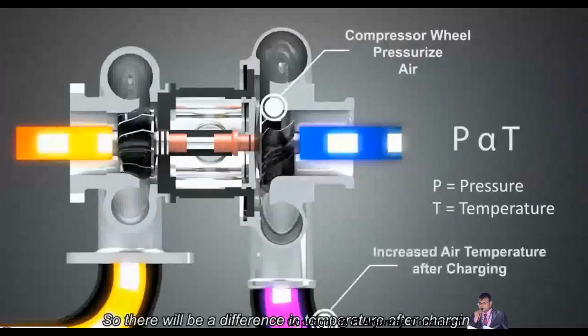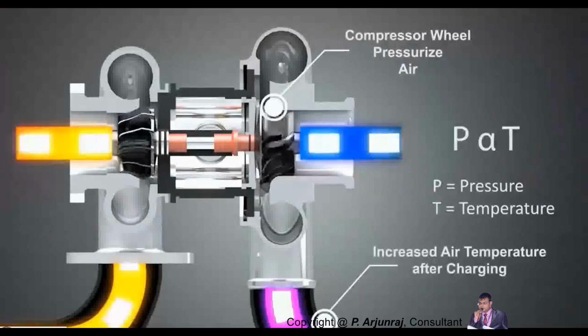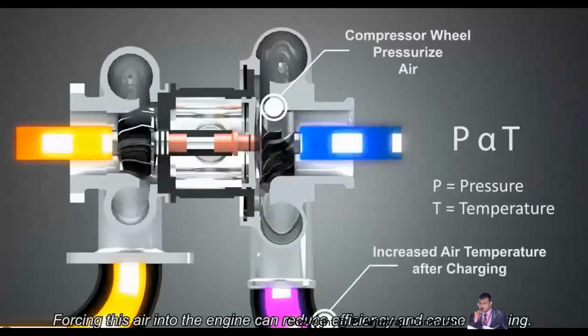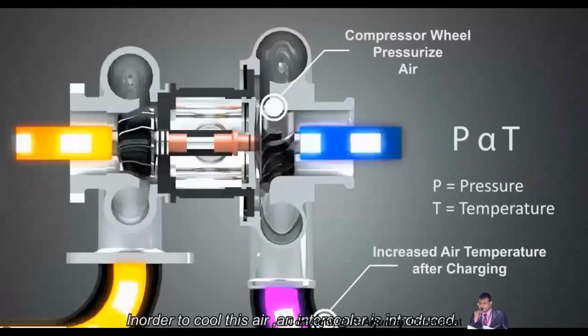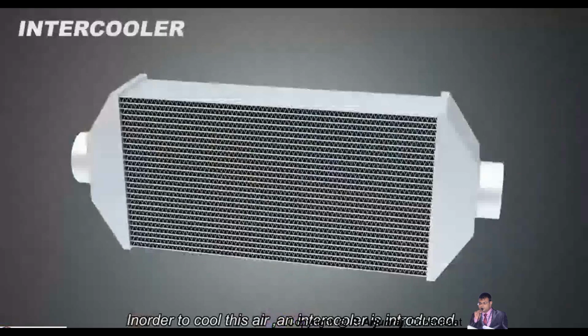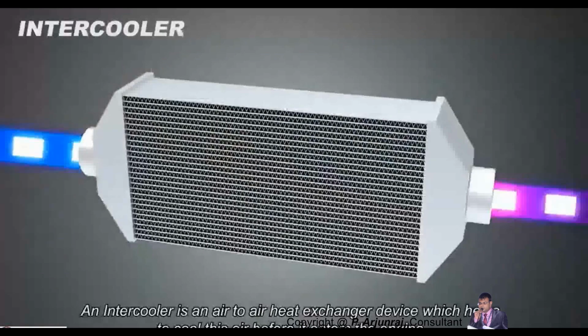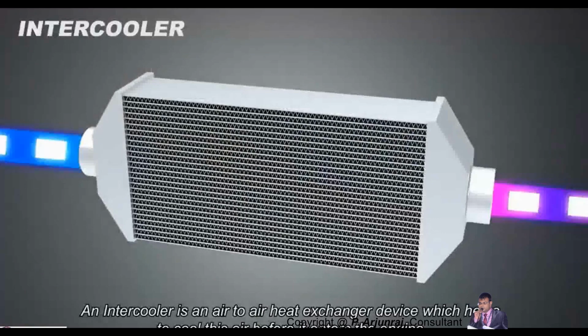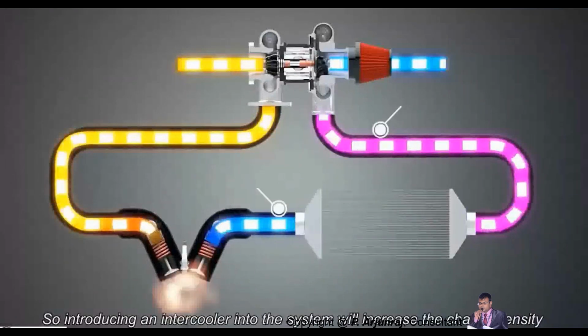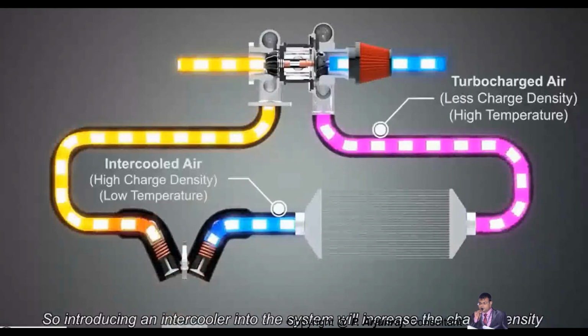So you need to reduce the air temperature basically, and you need to also increase the charge density. So this is where you are going for an intercooler. An intercooler is nothing but a heat exchanging device. It will reduce the temperature of the air, and it will increase the charge density.